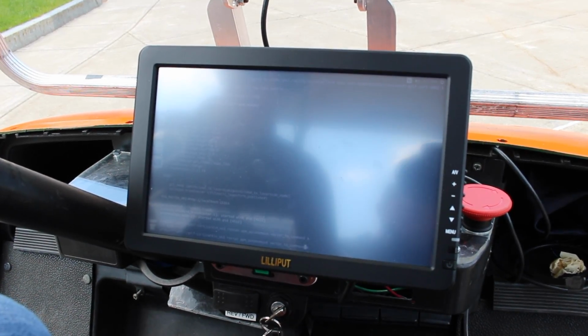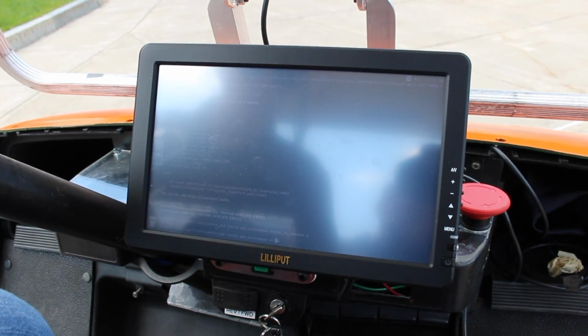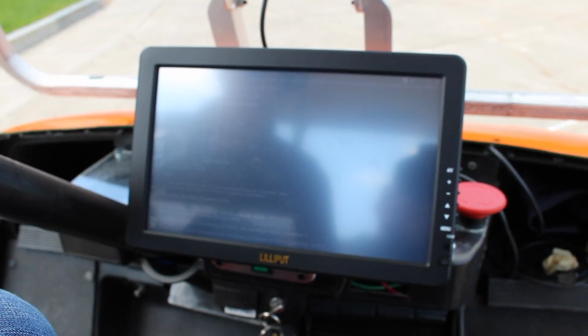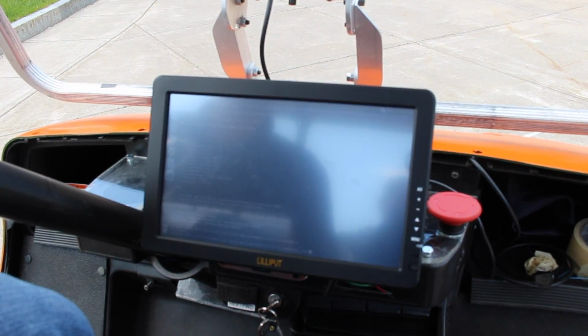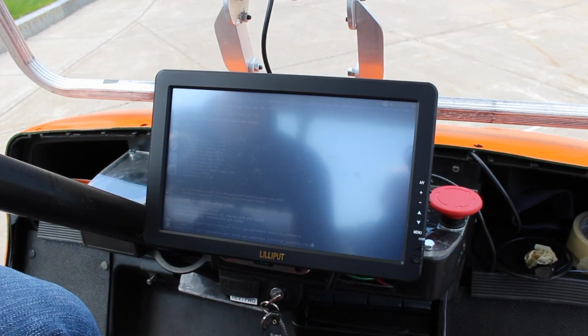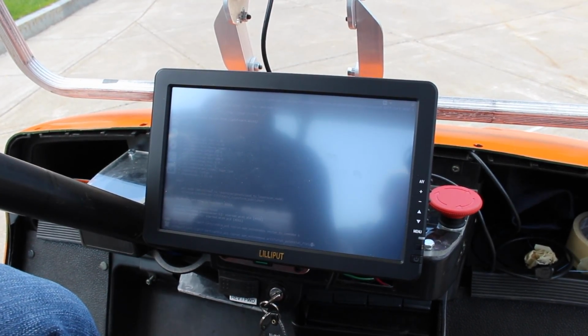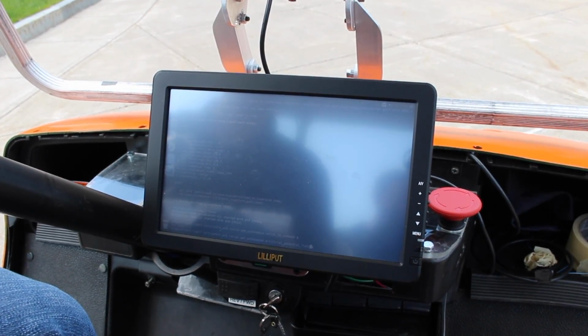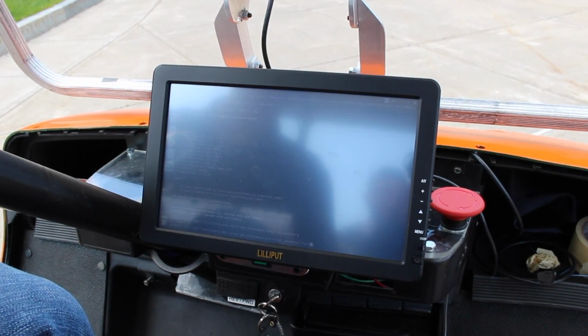And then the next one I'm going to run is also in APM autonomous, except it's the artificial potential field. What this is going to do is use the laser scan coming from the point cloud, coming from the LiDAR, to develop a set of environmental forces which are going to affect our desired vector to steer us away from obstacles. You can read more about that in the operations manual. So we're going to launch that off right now.